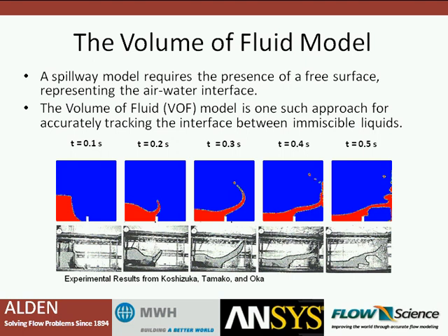But for problems in which you're concerned only with a steady-state solution, it is possible to perform a steady-state calculation. Specifically, the steady-state VOF option makes sense when your solution is independent of the initial conditions, and there are distinct inflow boundaries for each phase. One example is flow of water in a channel with air on top, which is basically what we're talking about today in a spillway.